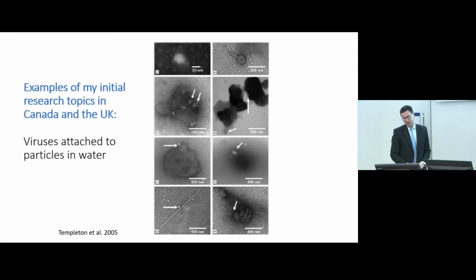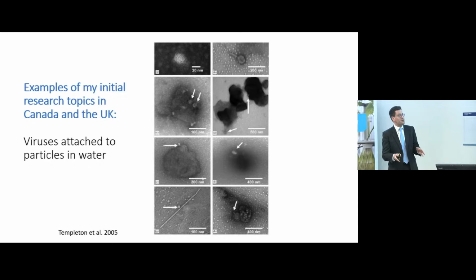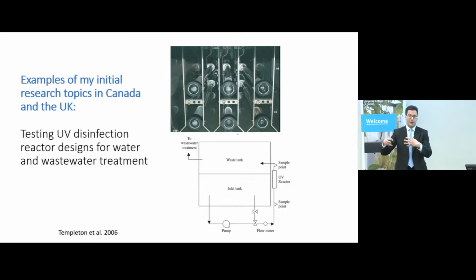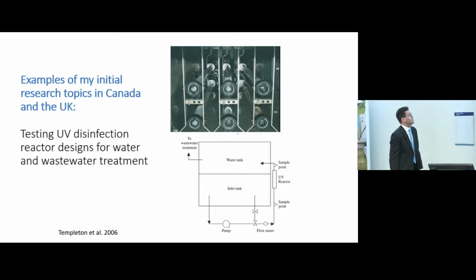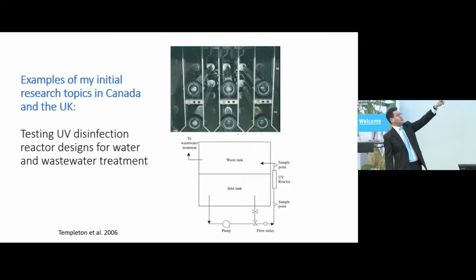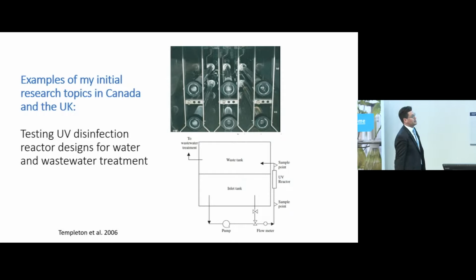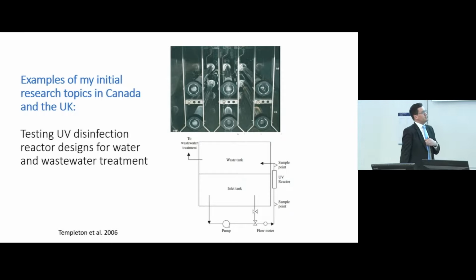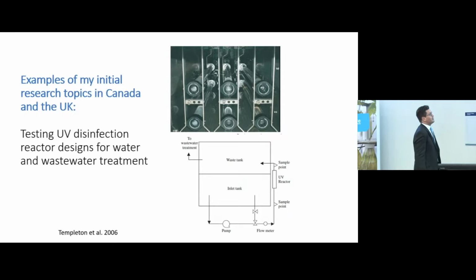Another great opportunity in my PhD was to get out of the lab and to actually do things at scale. I think that was another really valuable experience, to have the opportunity to do what we call pilot scale research. I worked with a company called Suntech Environmental, who design ultraviolet disinfection systems for water and wastewater. What they were interested in was designing these reactors. Those are UV lamps that you're looking at there. The water would flow past these lamps for a few seconds and get completely disinfected. And they were interested in what the flow rate through the reactor should be, how far apart the lamps should be, and how bright the lamps have to be in order to properly disinfect this water.